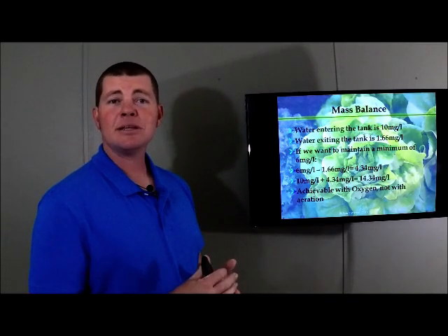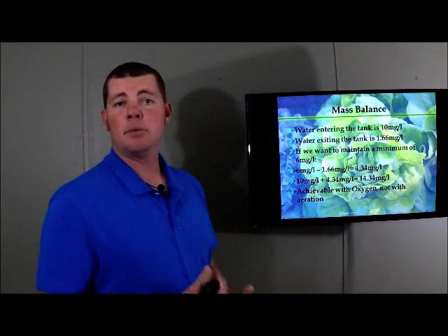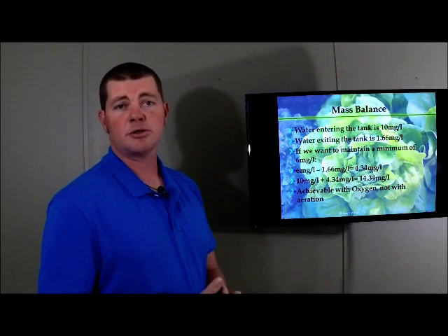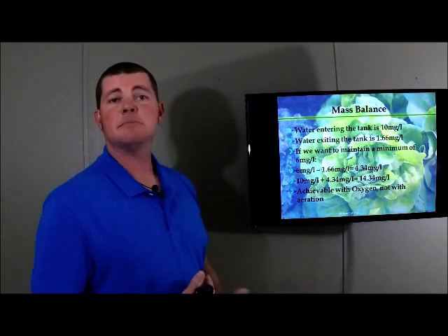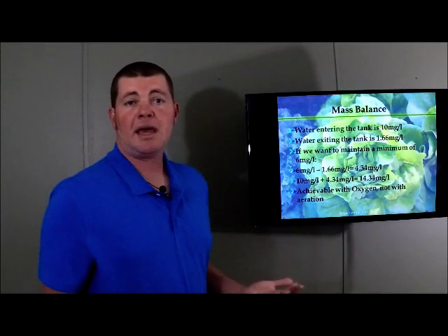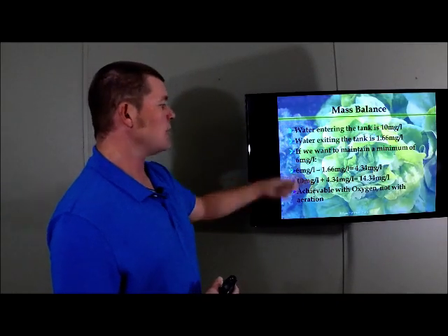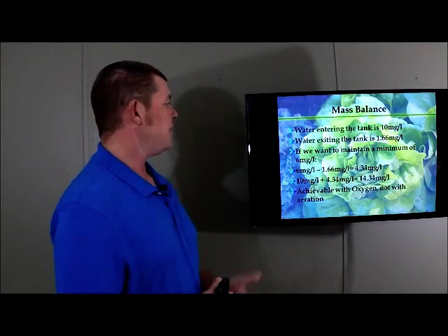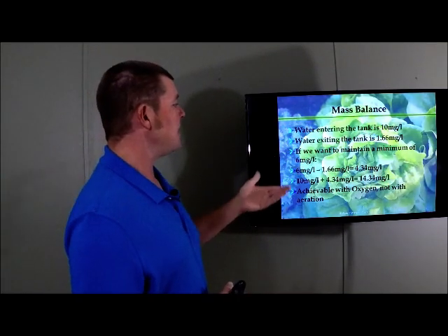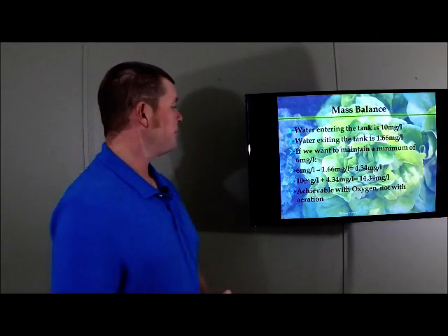If our injected water has an oxygen saturation of 14.34 milligrams per liter, then after the feeding and all of the processes in the culture tank, the water will leave at 6 milligrams per liter, which is completely acceptable because we went ahead and looked up the species we're culturing and we made sure of that. If this was 8 milligrams per liter, we could calculate it for that. If it was 3 milligrams per liter, we could do that calculation. So it's species dependent, but the math will give you the answer no matter what you go through.